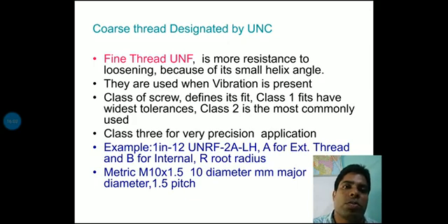Now, the class of screw defines the fits, and the fits may vary on the tolerance limit. The most commonly used class is class 2, and class 3 is for very precision applications, just like the 1 in 12 and so on.